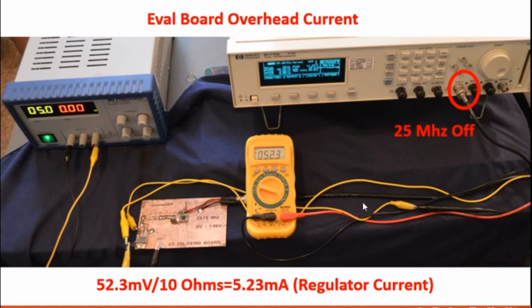If you notice in this particular clip, the 25 megahertz clock is off, so there's no dynamic power. We're actually driving CMOS logic inside the part when we turn things on to generate dynamic power for measurement.